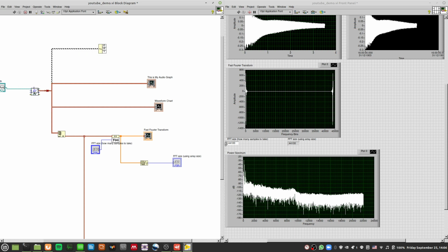So this wave reader file is actually giving a 1D waveform, but what data this little block here is expecting is a waveform. It's not a 1D array of waveform, it's just a waveform. So how do you actually solve this problem?